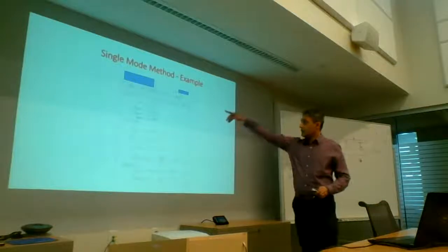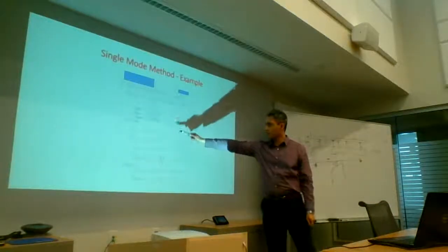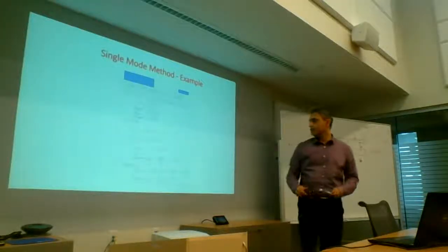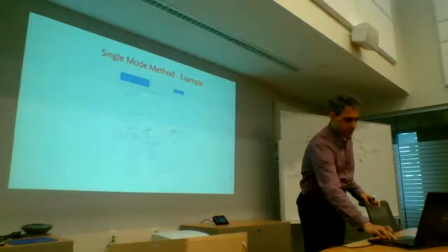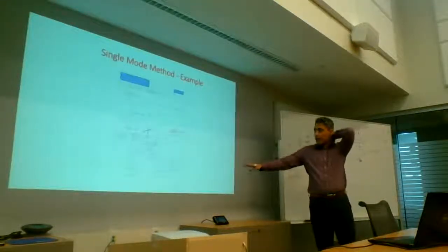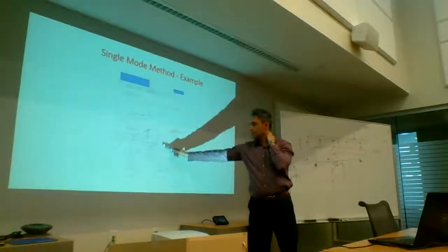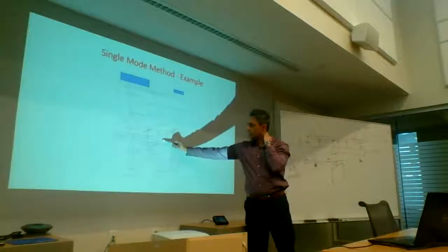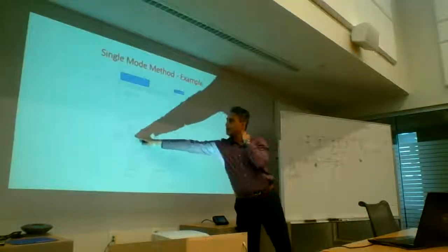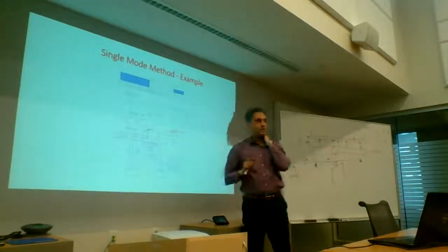So based on that, you can come up with the deck weight and the weight of the section 1, and then come up with an equivalent steel area. Same thing with section 2 and section 3. And this is where I'll spend a little bit of time. How do you model this? Again, you model it with stick elements. You can model 3 or 4 elements. Then you have rigid sticks that take you to the CG of the cap beam. So all these elements are pretty much rigid elements.